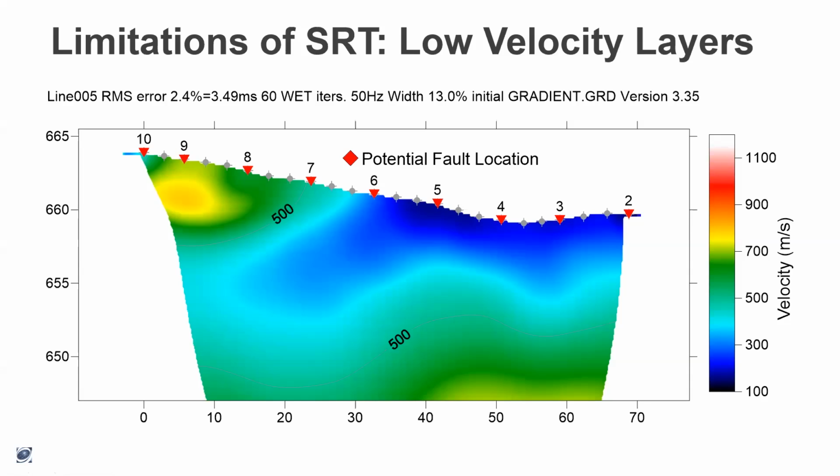carbonated soil that is typically very hard and has a very high velocity relative to looser soils. That being said, if you're able to put your array half on your velocity inversion, half off your velocity inversion, you do have a limited ability to image the velocity inversion and to be aware that it's there. That's what this situation is here.